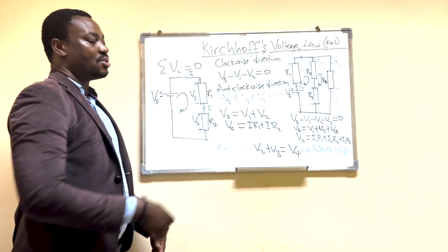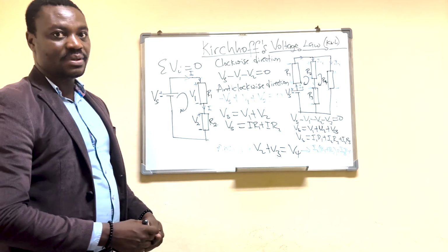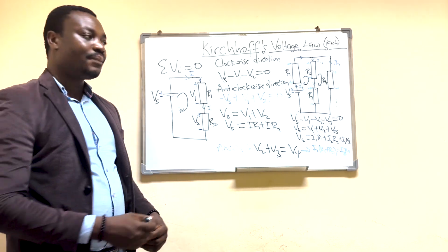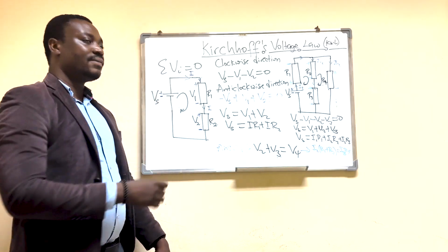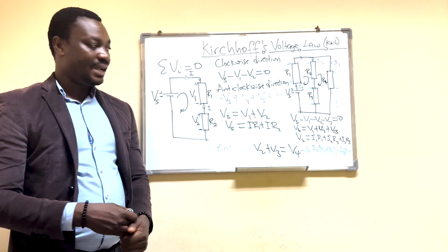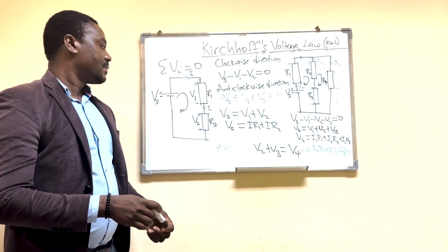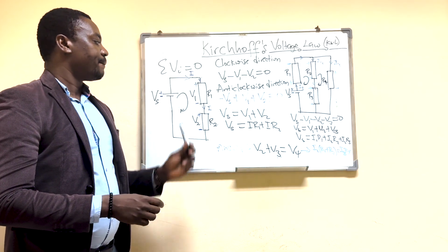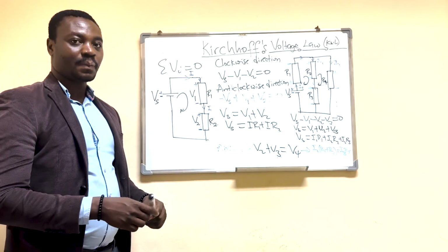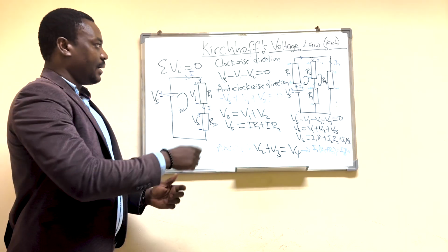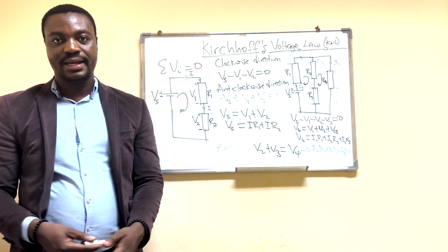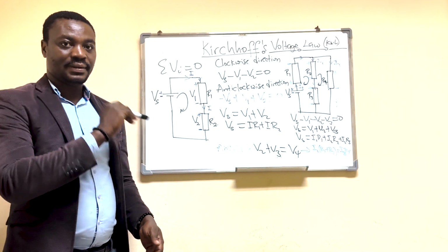The next step is now to do the algebraic sum. Algebraic sum here, we are going to consider minus to plus as rise and then plus to minus as drop, right? So, in doing the algebraic sum, we can go clockwise, right, or anti-clockwise, right?